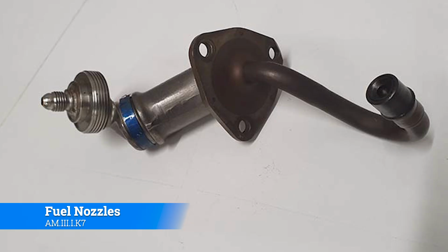Now this time you notice that it curves back, it comes forward, and it has a totally different nozzle on the front. There's no ports or anything. It's literally just a cone with a guide post in the middle of it to create the right spray pattern. And here's the thing, this isn't going to be the only one on a CFM56. There's going to be several of them. And so that is set up so that it goes in just the right spot, that sprays the fuel in just the right way, so that it mixes just correctly and then fires off as needed.